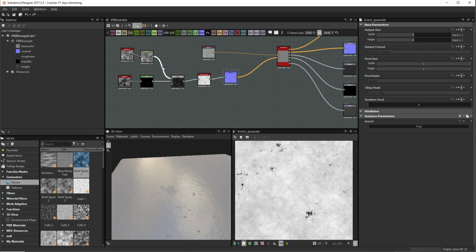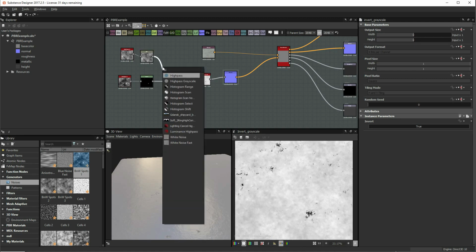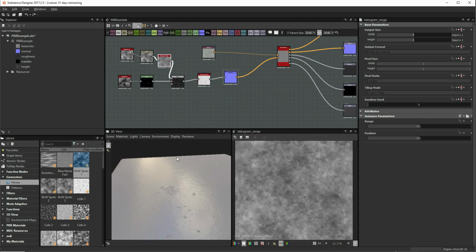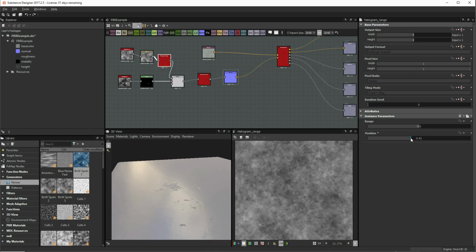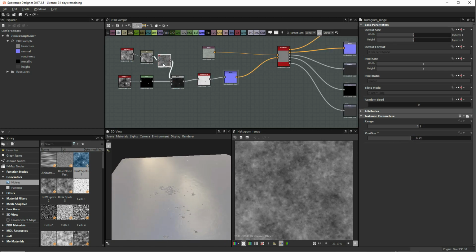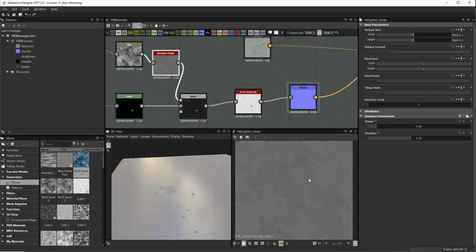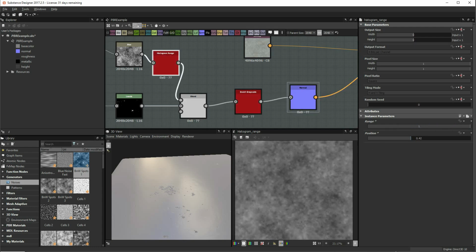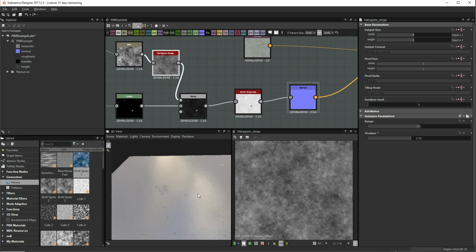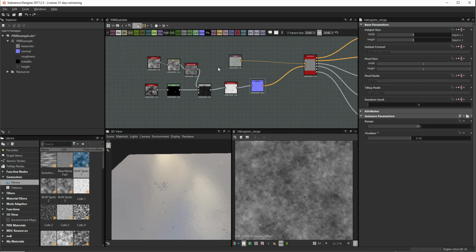What I might do though is press space again and type HIST, which is a really nice tool to do very fine adjustments to the intensity of the effect. Sort of bring down the position. There's two of them, the histogram range and the histogram scan. The range allows me to limit the range and to make very subtle effects, a very grey image. Or here, when I move it to 1, I have the full scale of the image. So this is really very good to do fine-tunings. So anyway, I could carry on for hours. So I'll move on, and